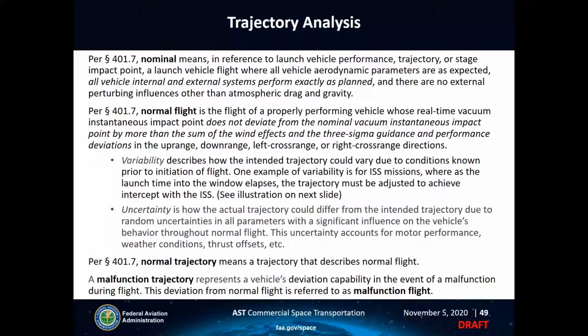To begin, we'll go over some definitions of commonly used terms to get us all on the same page before covering trajectory analysis for normal flight, followed by trajectory analysis for malfunction flight. In reference to launch vehicle performance, trajectory, or stage impact point, nominal means a launch vehicle flight where all vehicle aerodynamic parameters are expected, all vehicle internal and external systems perform exactly as planned, and there are no external perturbing influences other than atmospheric drag and gravity.